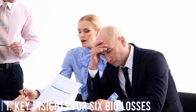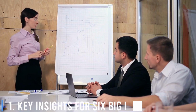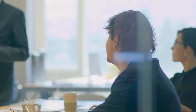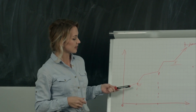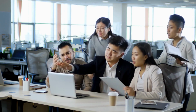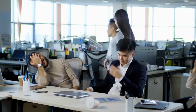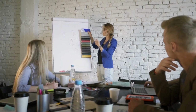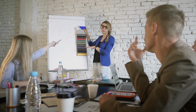Number 1. Key insights for 6 big losses. Monitor the constraint. Every manufacturing process has a constraint, which is the fulcrum, i.e., point of leverage, for the entire process. Measure 6 big losses at the constraint and focus your improvement efforts to improve the constraint. This will be the fastest path to improved throughput and profitability.